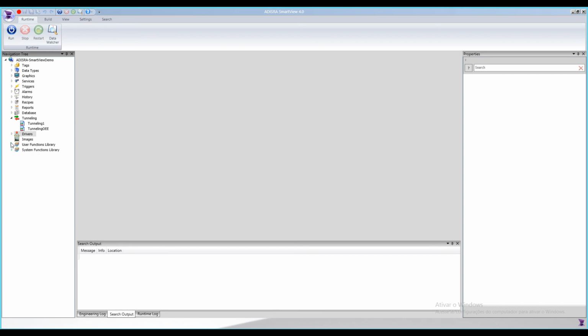Something that I left for later is the OPC communication. It is used a lot in most factories, and this can be done if you right-click under the drivers and add a new folder. These are some of the drivers that were already implemented, but you can also have OPC clients. You're going to need a client since you'll be connecting to a server, and you can create OPC DA or UA or historical DA.